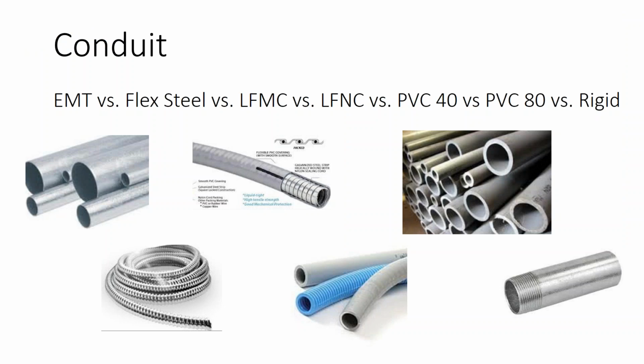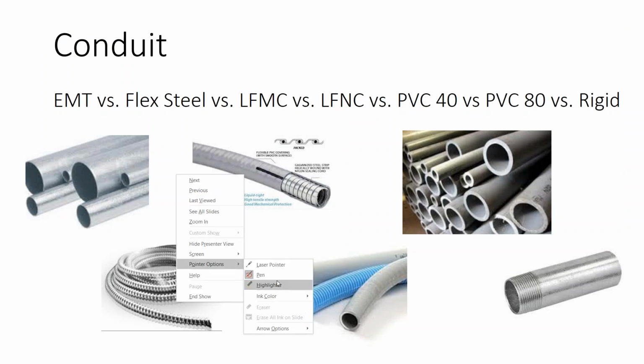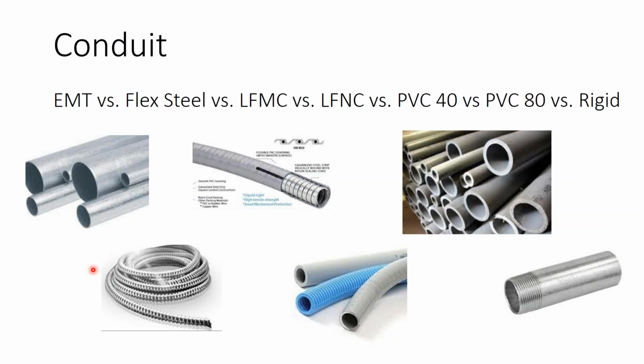You have to go into metal when you're in DC wiring. Not that I think inspectors today will be picking up on it, but technically, inside a battery room, because DC has to be inside metal conduit, it's common to see this metal flex conduit being used. Technically, inside your battery room, you should be using this plastic flex conduit with the metal inside. It just has a plastic layer around it. It's more expensive.